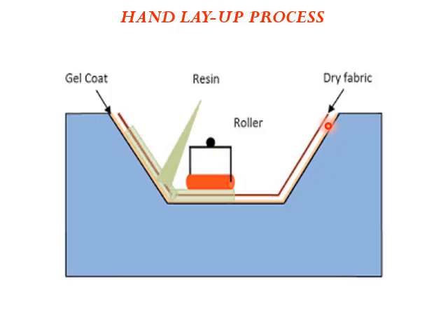Rolling over the sandwiched reinforcement and matrix material will also remove entrapped particles. If there are any air particles trapped in the resin and the fiber, when we roll, those trapped air particles are also removed.